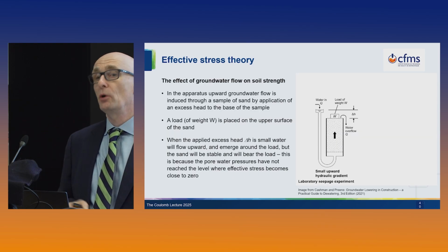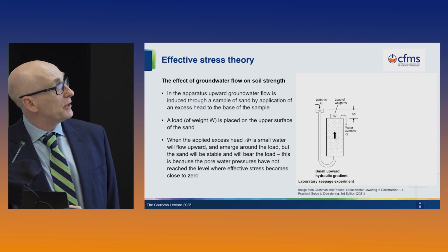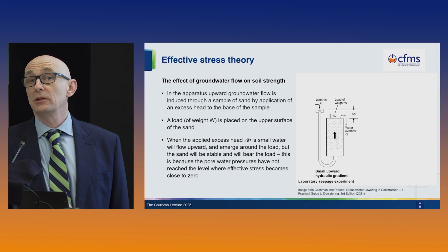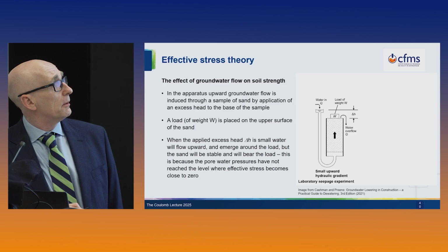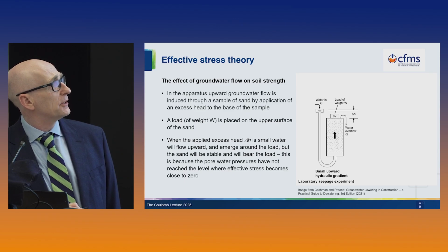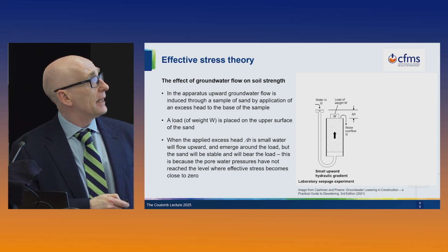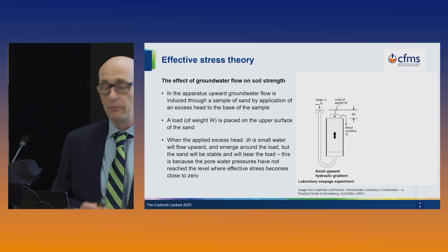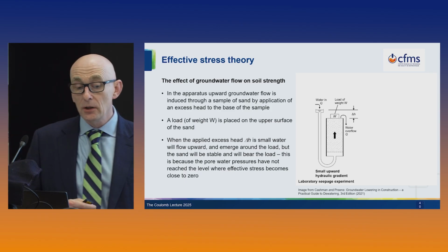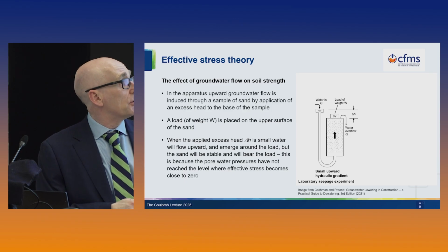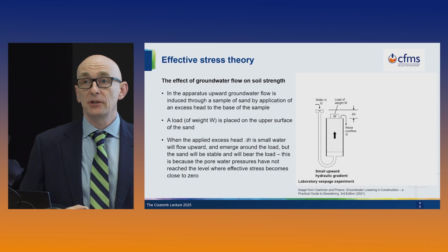So let's consider the effect of groundwater flow on soil strength. Let's imagine a laboratory experiment that's not very dissimilar to Darcy's situation, where we have a vertical cylinder of sand and we're going to feed water in at the bottom. So we're applying an excess head delta H, we pour water in, continuity of mass tells us the water must come out, and in this situation where the excess head is small, the weight that we sit on top of the sand will probably be stable, because we've got water flowing over the top, but the pore water pressures here won't be too high, and the situation will be stable.